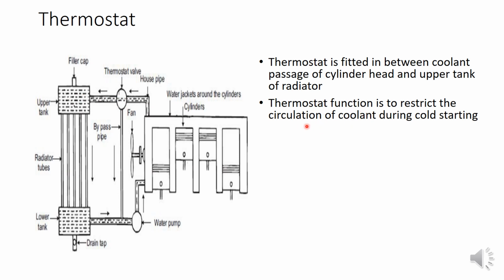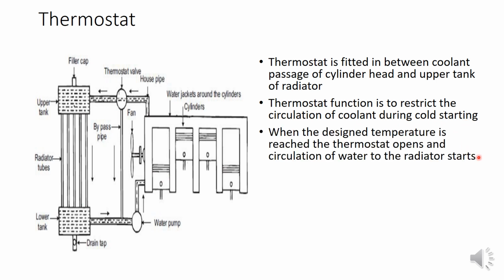So if you are in cold starting, what will happen? If you circulate the coolant, the temperature will reduce further. To avoid that, we want to stop the flow of water to the radiator and this system in cold starting. That is done by the thermostat valve. And it automatically opens when the temperature increases, and it allows the circulation of water. So once the cold starting is over, the engine works for some period of time, the temperature increases and it automatically opens and allows the flow of water.